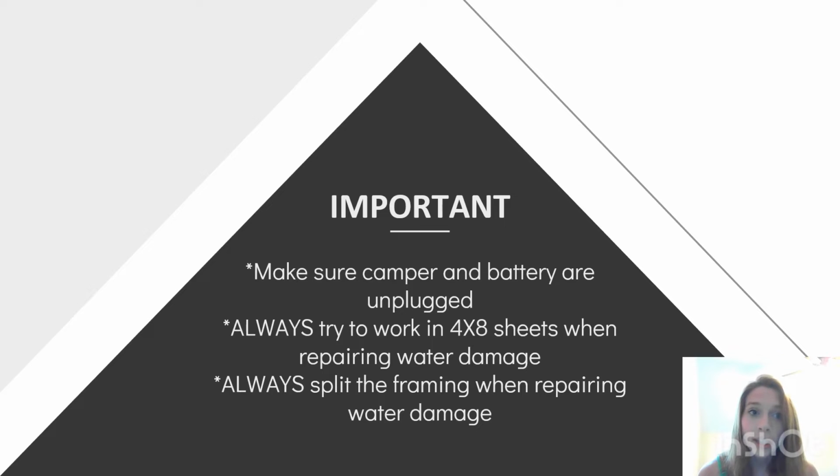Next, always try to work in 4x8 sections, always. So campers are built using 4x8 sheets, and it's a lot easier to replace the whole panel than it is to cut small sections out and try to repair it that way. It's also going to make your camper look like there was never any water damage at all if you repair it based on the dimensions that the manufacturer built on.